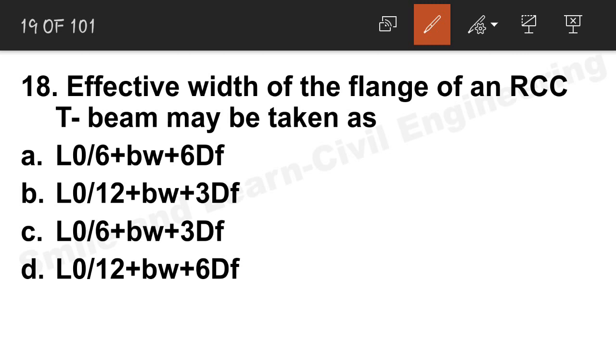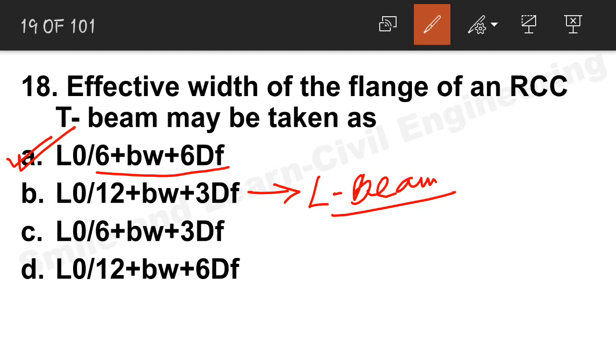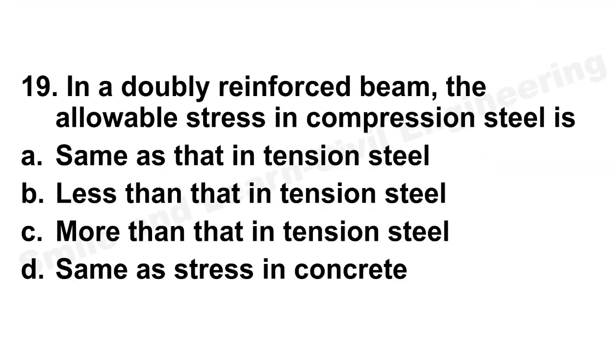Okay, so the correct answer for a T-beam is L0 by 6 + BW + 6 DF, and don't forget, for an L-beam it is L0 by 12 + BW + 3 DF. Okay, this is for the L-beam. Next question, question number 19.